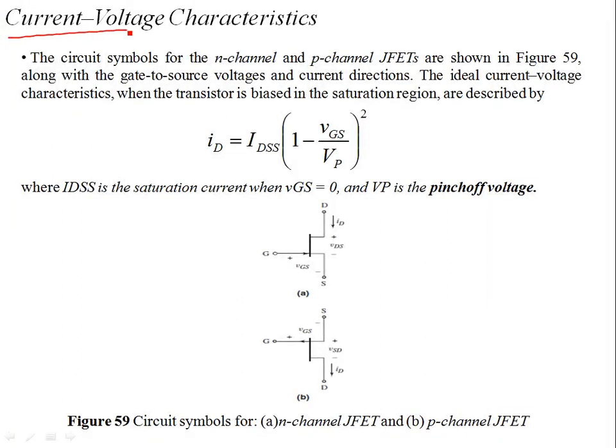With the current voltage characteristics of JFET devices and MOSFETs. Now, we've already talked of the construction of both devices. Both are field effect, so you need the field at the gate to control the channel resistance or to moderate the channel conductance. As an effect of the applied field at the gate, you control the flow of charges, or you control the current. This is why these devices are known as field effect devices or field effect transistors.